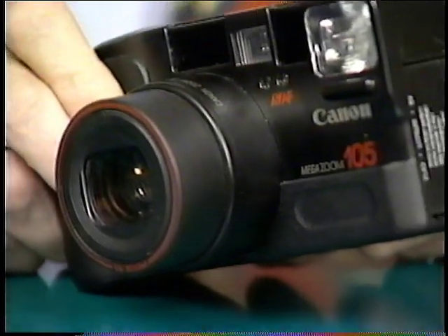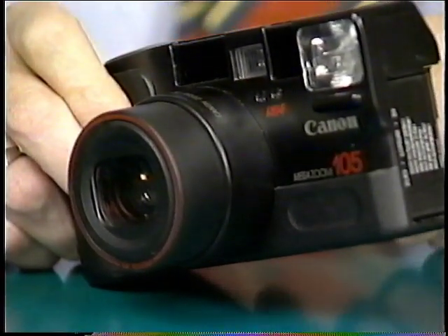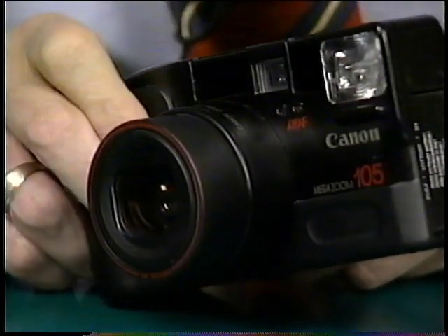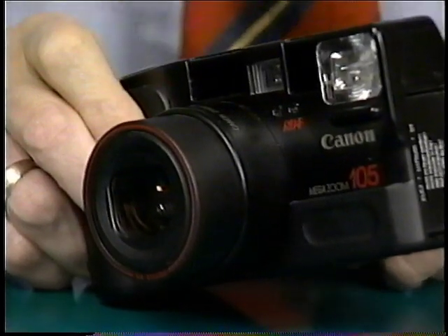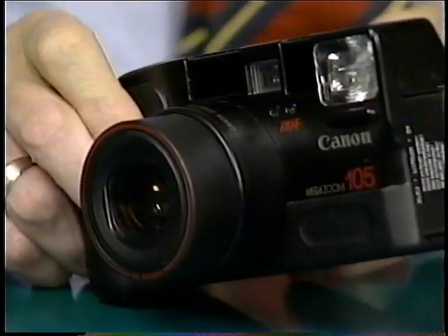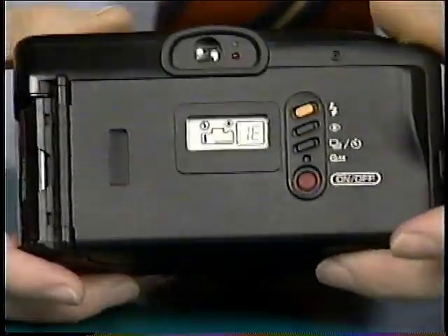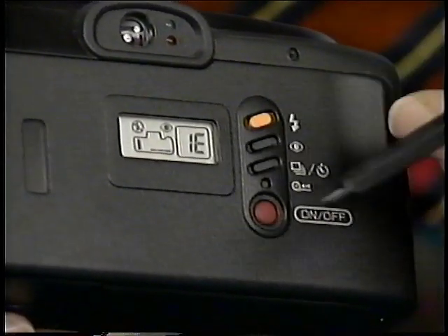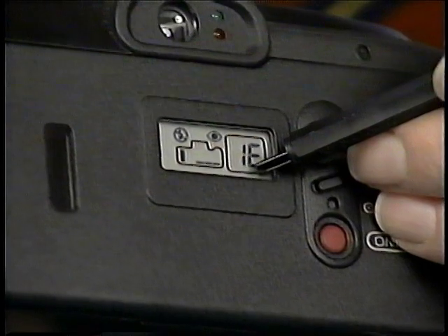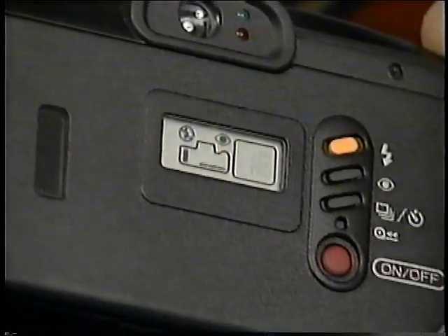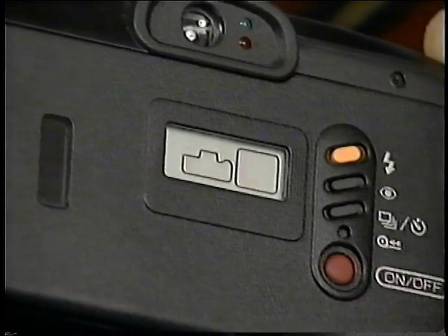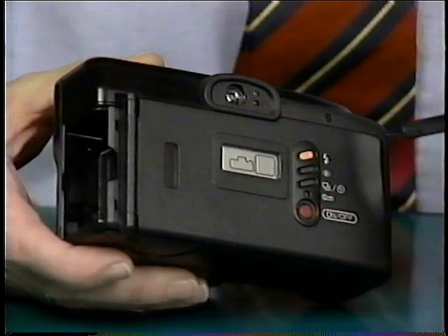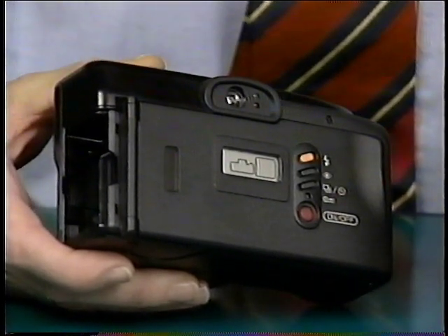We reset the system, installed the battery again, and I'm going to press the power switch one more time. You can watch the lens and listen. And you hear the motor running without the lens moving, which is why we got the error, the E1 message, indicating that the lens did not extend. Anytime you see an error code in a camera, you can reset by removing the battery and starting again. If on your second try you get the same error message, the camera will need service.